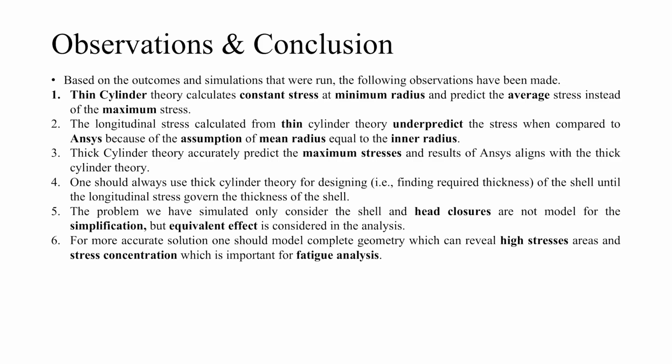The problem we have simulated only considers the shell, and head closures are not modeled for simplification, but the equivalent effect is considered in the analysis using the thrust force. For a more accurate solution, one should model the complete geometry, which can reveal high stress areas and stress concentration, which is important for fatigue analysis.